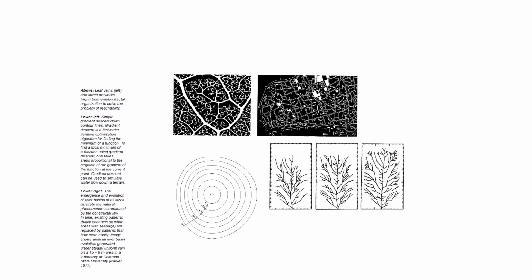And there are some other resources here. Why is that flow interesting in the context of design, and maybe landscape architecture? It's because we can use flow, or gradient descent, to simulate rainwater, rain flow. There are different theories about how this liquid flows down the terrain, including erosion. So the material is also flowing down the terrain, but also taking away pieces of the terrain, the granulate or aggregate that the terrain is made of, and that is how channels are formed.